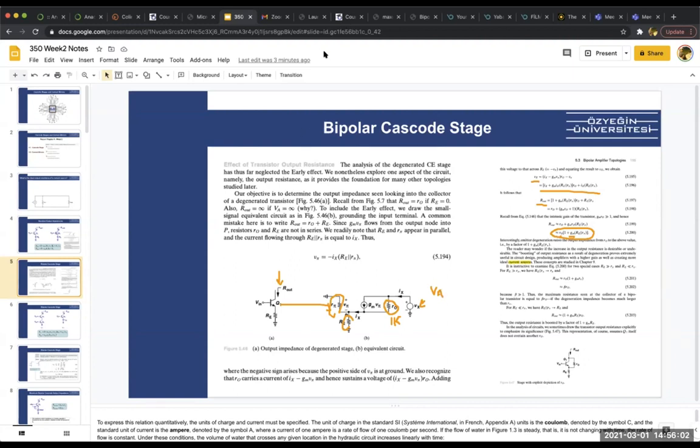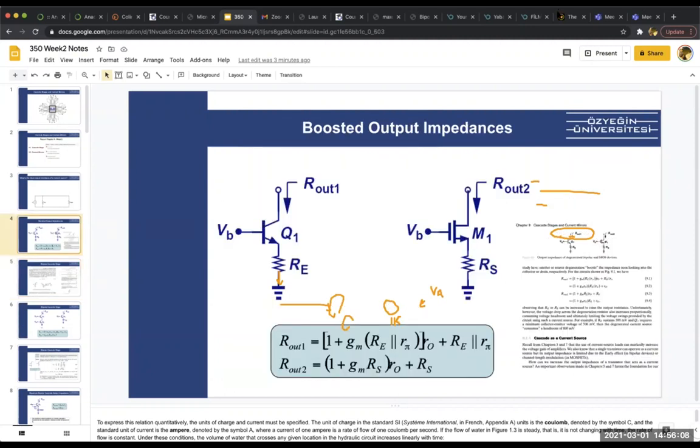So going back to the original slide, as you can see, for BJT and for CMOS, this R out can be different. Why? Because in BJT we have R pi factors, but in the CMOS we don't really have any R pi. Therefore the R outs might be slightly different. One of your probably first problem sets will be to compare these two circuits, or maybe more complicated ones, and figure out which R out is bigger.